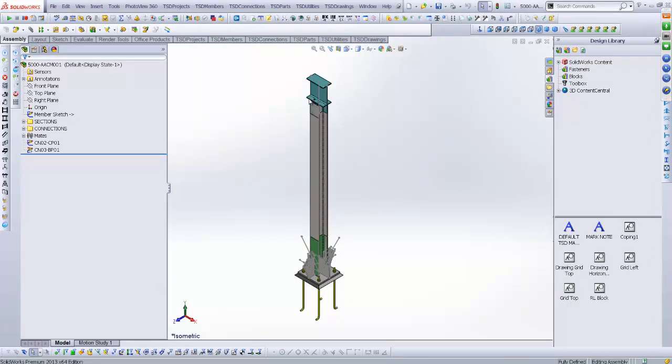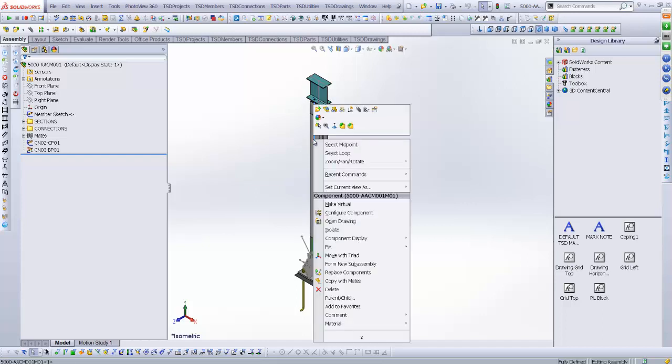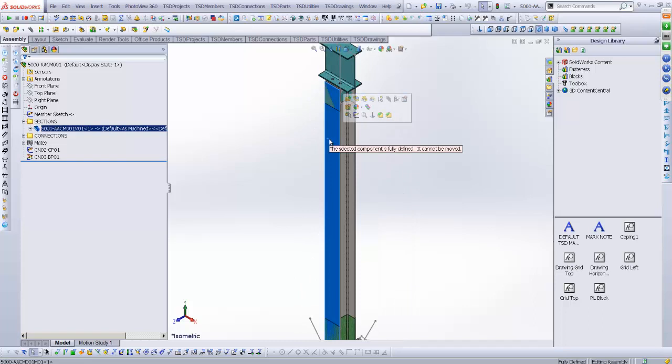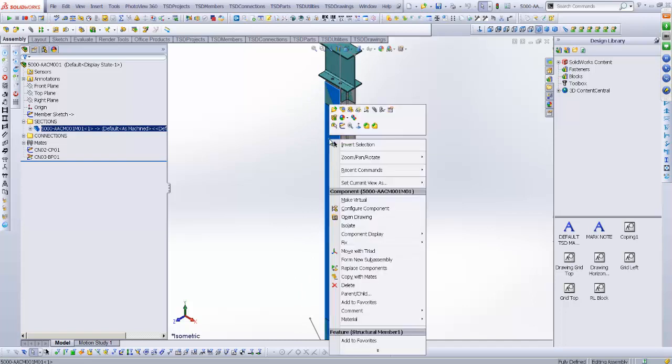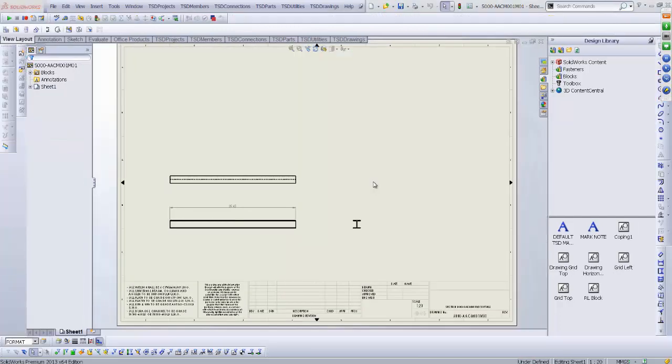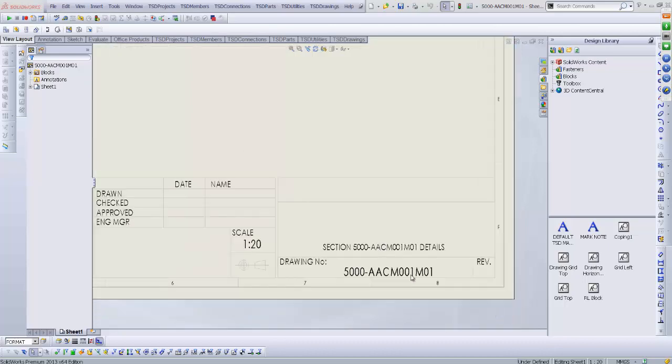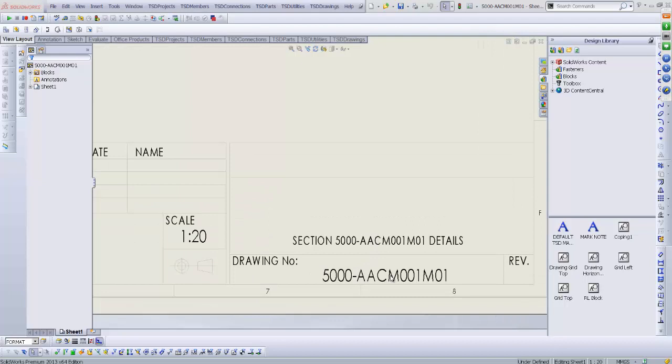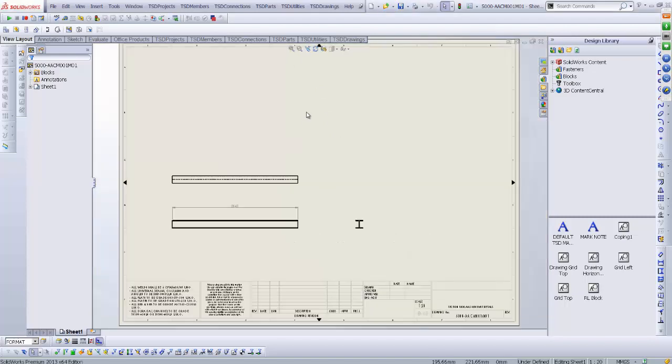Now also too, with that template for a welded member drawing, we've also got the member section drawing, which is the steel section that forms the major part of the component of the column. And if we open up the drawing associated to that as well, there's no marking or mark numbers or anything associated to this. But the template itself will also need some sort of a change down in the bottom right hand corner, because that's also set up to pick up the default mark name.